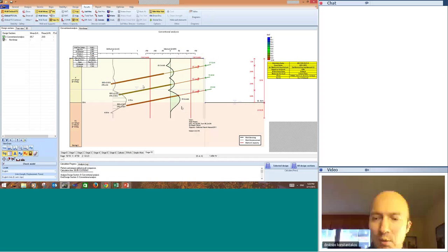So you can see the bending moments: Caltrans 65.6, FHWA 33.7, simple span moment 51, and the Caltrans with negative moments 57.6. And you can also compare the reactions on the supports, the stress checks, and your wall embedment safety factors.